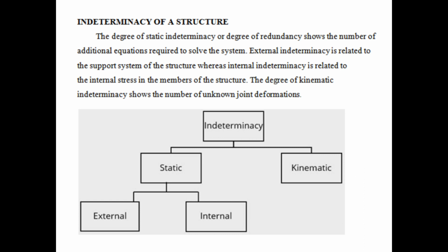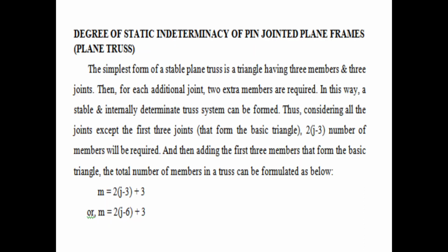The degree of kinematic indeterminacy shows the number of unknown joint deformations. So this is the flow chart: indeterminacy, that is static and kinematic. For static, there is external and internal. And next, the degree of static indeterminacy of pin-jointed plane frames, that is plane trusses.